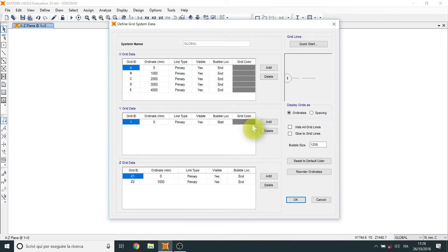Pay attention, if you want to validate this frame with the results of the displacement method, take in mind that you don't have axial deformability if you consider a fixed joint frame. So the only movement is the rotation of this joint.